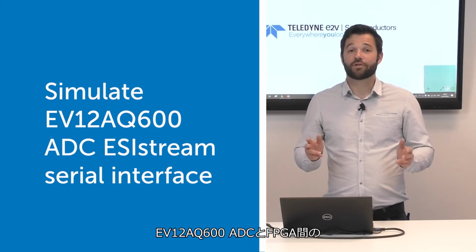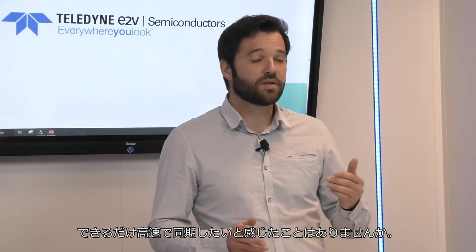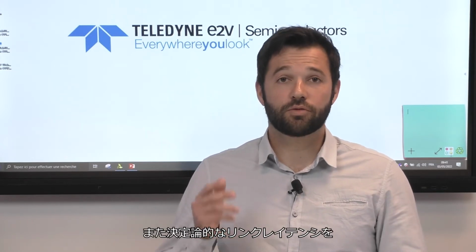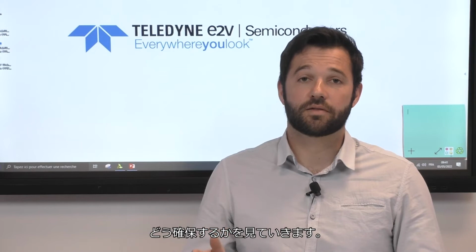Does your application require controlling sample propagation time between the EV12AQ600 ADC and an FPGA, or synchronizing the ESIstream serial link as quickly as possible? In this video, I will demonstrate in simulation how the AQ600 ADC and ESIstream serial link protocol will help you guarantee both a short synchronization time and a short total link latency. Then, we will look at how to ensure a deterministic link latency.